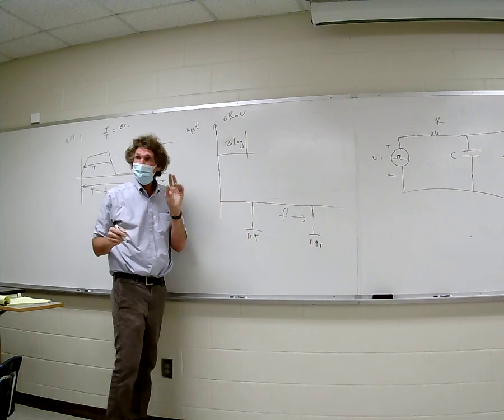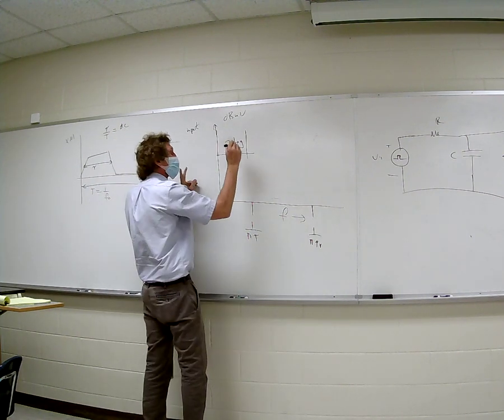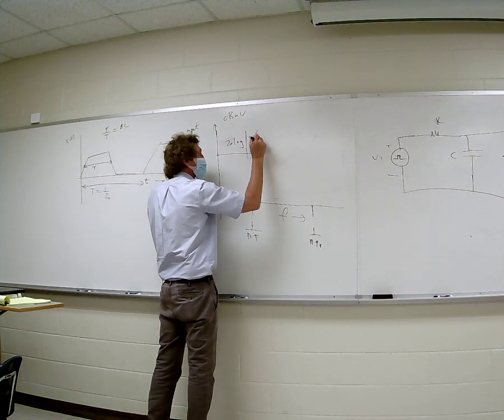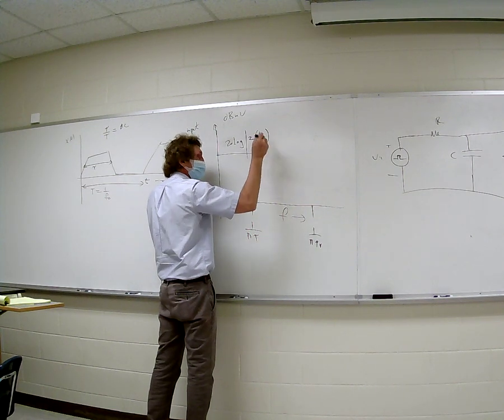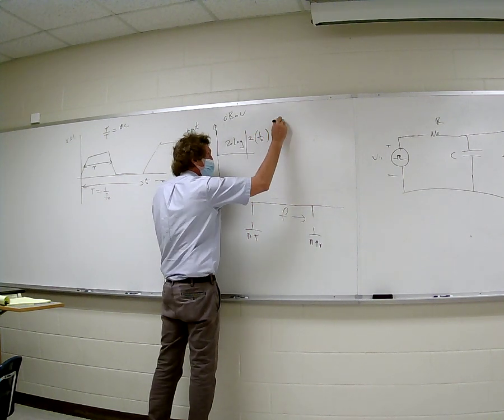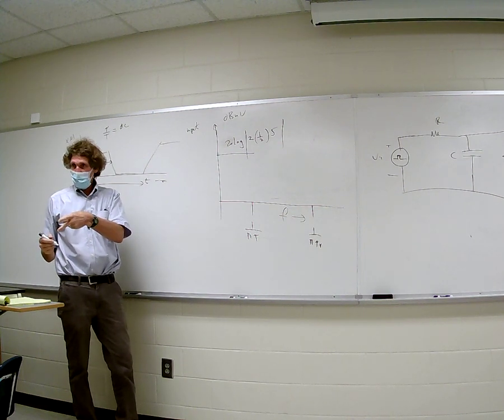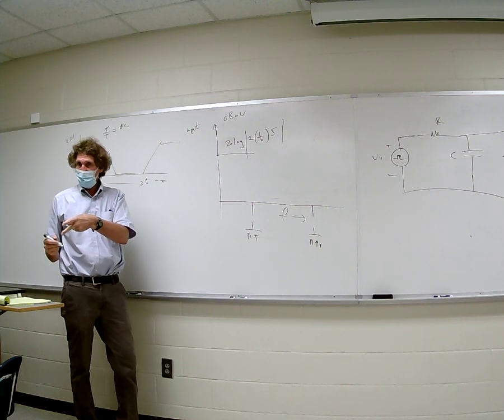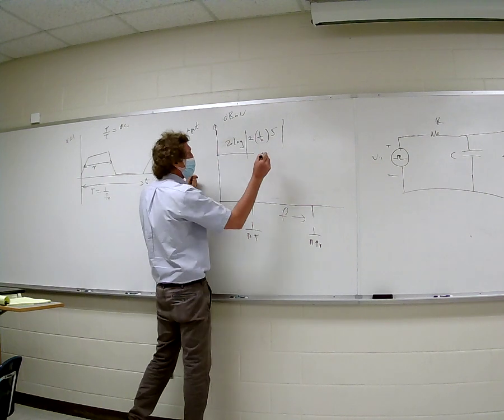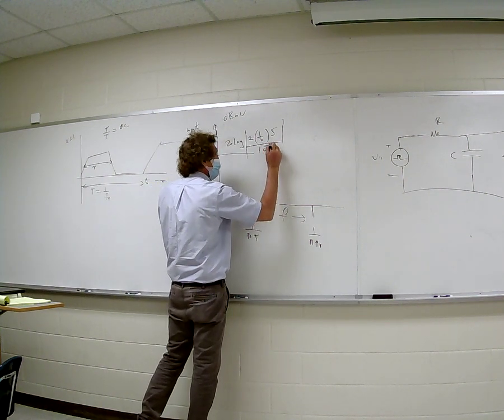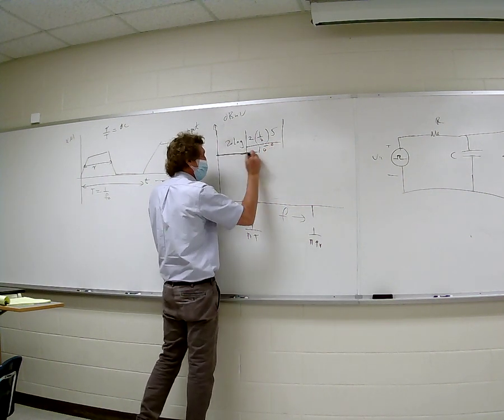Remember how we did this? And now it's going to have 2 times the duty cycle, which is 1/2, right? Times the magnitude, which is 5. But we have to divide that by 10 to the minus 6 because I want dB microvolts. You all with me? So then I divide this by 10 to the minus 6. That's going to give us our base level here.